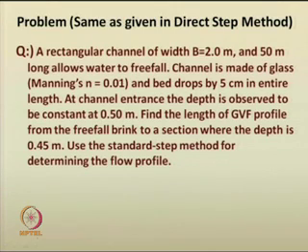We have asked you to find the length of the gradually varied flow profile from the free fall brink to a section where the depth is 0.45 meter. So, here you use the standard step method for determining the flow profile.